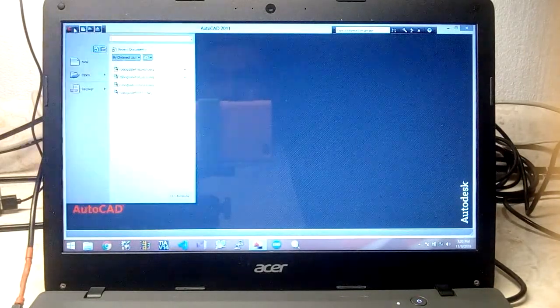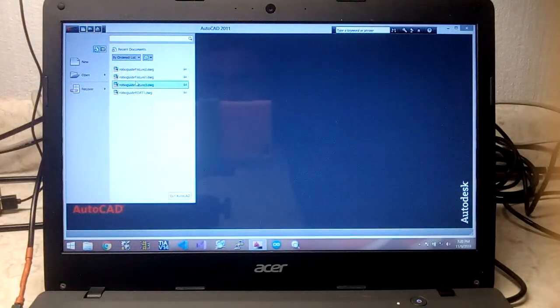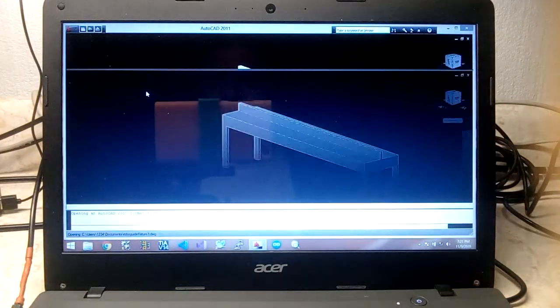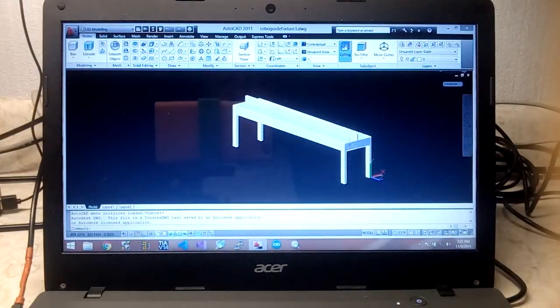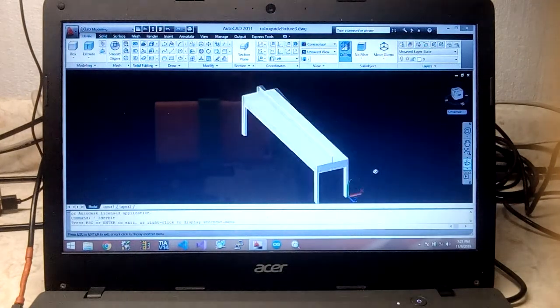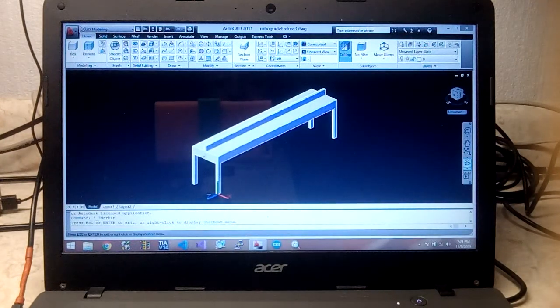And for last, I have a conveyor, which is a double twin conveyor. Actually, this is a very simple representation of it. It's actually a double conveyor. One side moves one direction, and the other one goes in the other direction. They have servos attached to it, so it will advance a certain length depending on the part size. And I had photo eyes on them, knowing that there's a part present, and so on, and one at the end telling you the conveyor is full of parts.